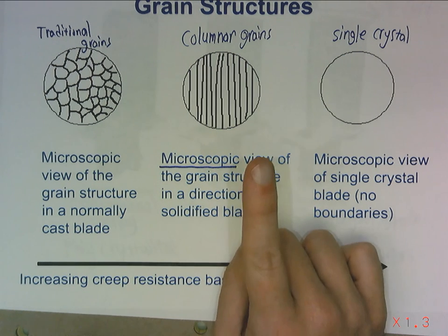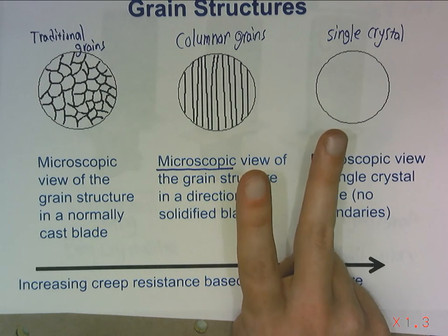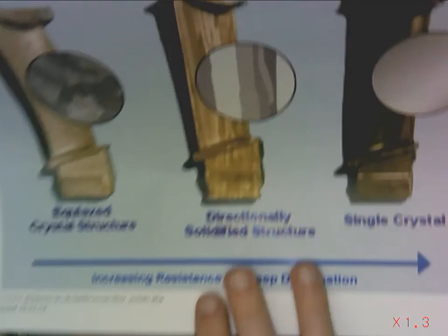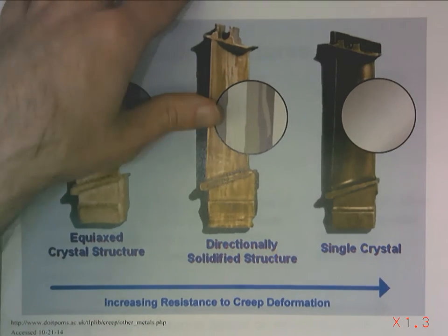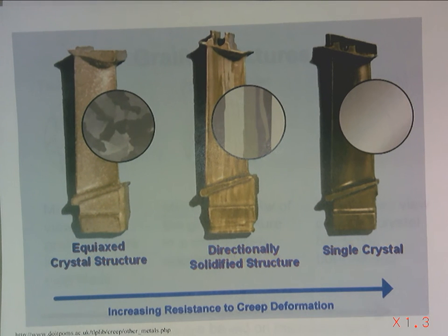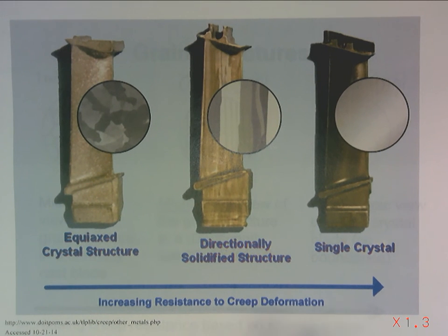So we can play with the microstructure and we can play with the chemistry to resist creep failure. Here's how we adjust the microstructure. I'll show you this slide, by the way. Right? Hey, real microscope pictures based on real turbine blades. So, there we go. But we can also play with the chemistry. We can increase the melting temperature. And that's our two big ways to resist creep failures in situations when we cannot lower the operating temperature.